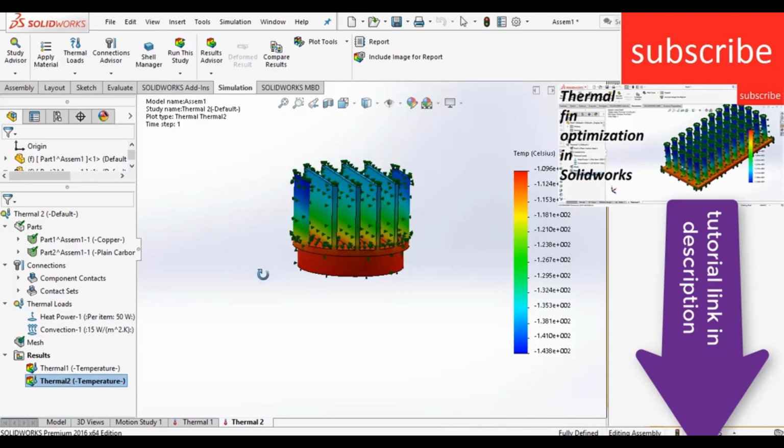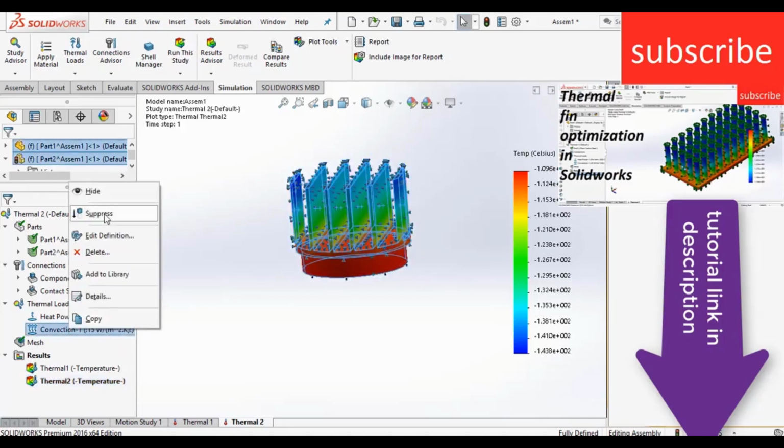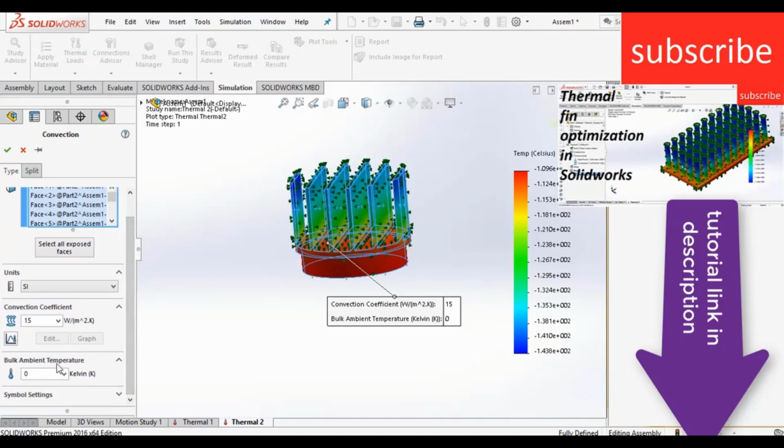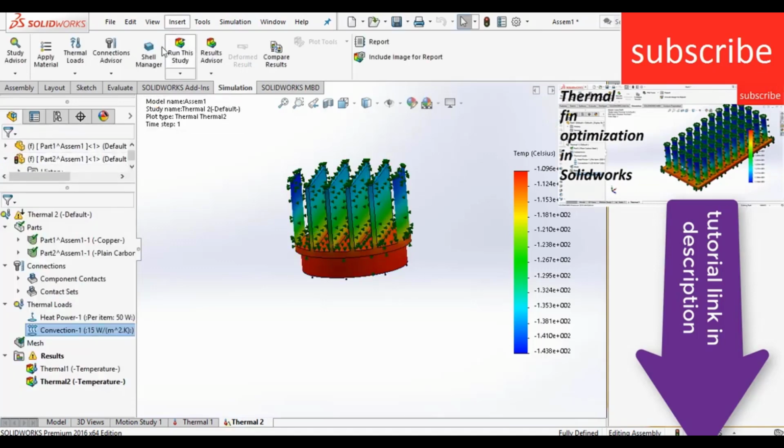So basically what happened during convection, right click on convection, click on edit definition. Here you see the bulk ambient temperature. Bulk ambient temperature basically means that it is occurring at a temperature where the room temperature is 0 Kelvin. You know that 0 Kelvin is a temperature that can't be achieved in real life. But here SolidWorks by default takes the bulk ambient temperature as 0 Kelvin. So change this value to 300 Kelvin, that is near about 27 degrees Celsius. Click OK. After that, click on run the study.